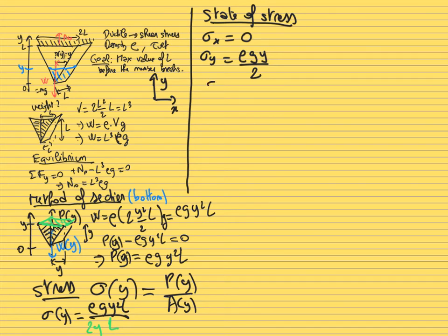We are just missing the shear stress, but in this case there is no shear stress. It's just an axial load problem, so there is no shear stress. Okay, so now we have the state of stress. We said that this is a ductile material, so it's going to break due to shear stress. But in this case, there is no shear stress. It's only pure tension along the y-axis.